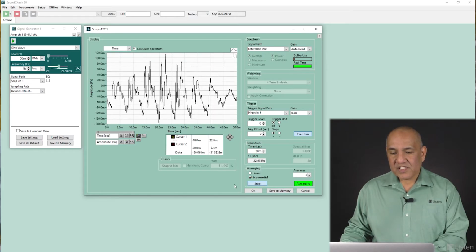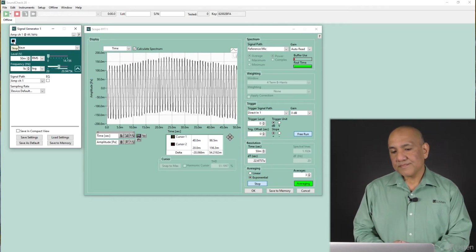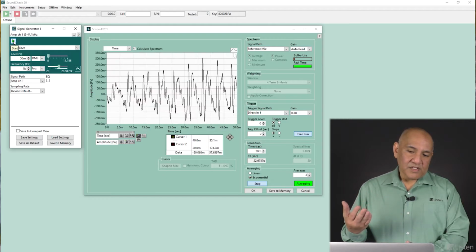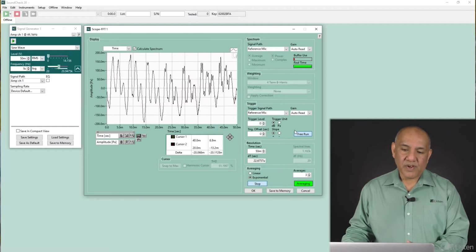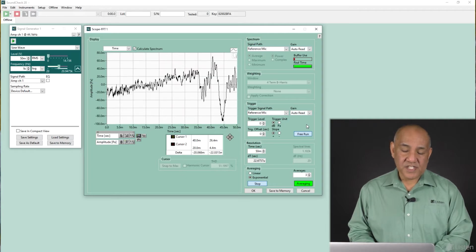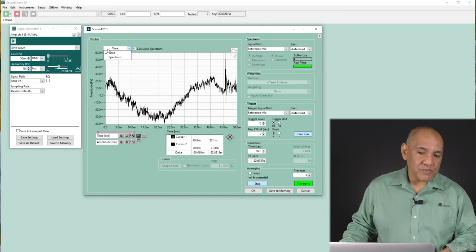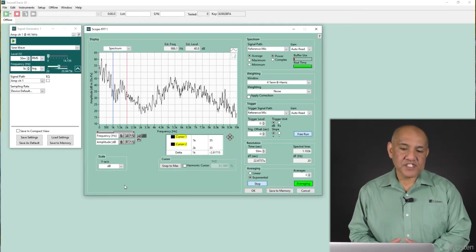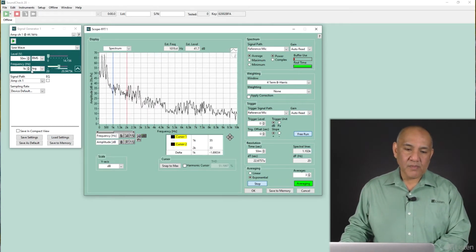Here I'm just doing an exponential averaging, and I will play a single 1K tone. Okay. I could also set this up, as you see on the right. I could set some level for input triggering, so the instrument only triggers on some type of signal input. Okay, so this is the scope. Let's switch over to the spectrum analyzer. Okay, and again here, now my x-axis is changed from the time domain to the frequency domain. Let's just look at that really quickly. I'll play a 1K tone.